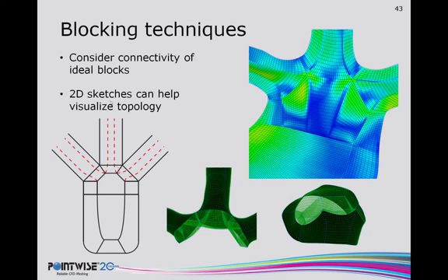So you can then get out a sheet of paper, try to do some 2-dimensional sketches, and say, okay, well, we're also going to need an OH topology here, but then it's going to need to combine down here at some sort of end cap, since we can't have an edge on this outer feature here because it would produce highly skewed cells.